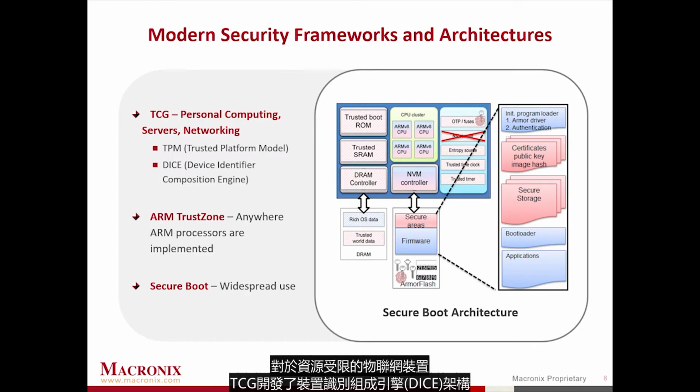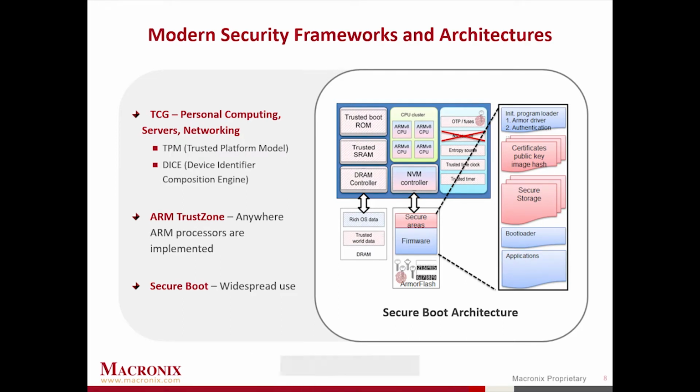For resource-constrained IoT devices, TCG developed the DICE architecture, or the Device Identifier Composition Engine, with minimal silicon requirements to achieve enhanced security and privacy. Even simple silicon capabilities combined with software techniques can realize enhanced security by implementing a strong device identity, attesting software, and safely deploying updates.